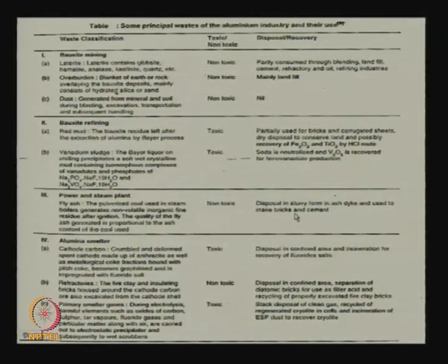People are finding use for fly ashes, but there is a problem here. In many countries, say in Europe, Poland and all, they do not allow use of fly ash bricks for making houses because they are radioactive. They are allowed for making roads and other things, not at all for houses, not where too many people are coming in that environment. In our country, we still do not have that restriction.